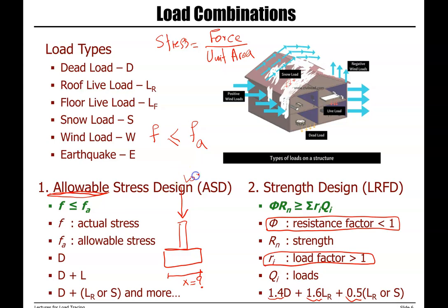This load here, the load applied from the superstructure divided by the area of our footing, should be equal or less than the allowable bearing capacity, which we calculate using properties of soil. So this is the one that we will use again in this class.